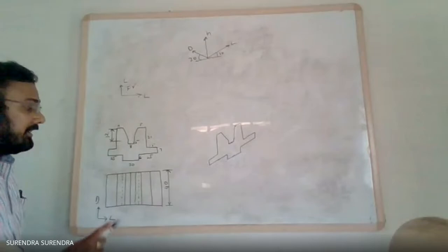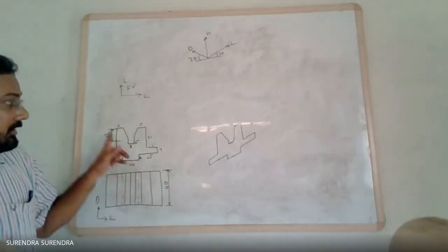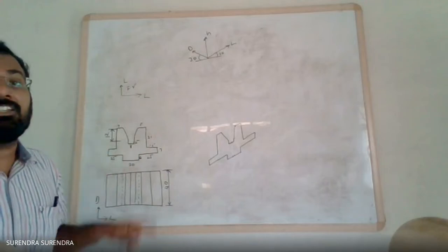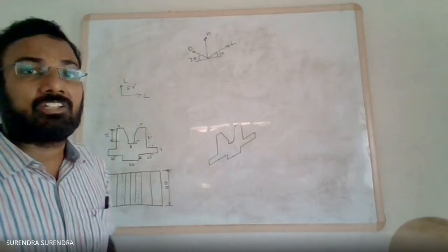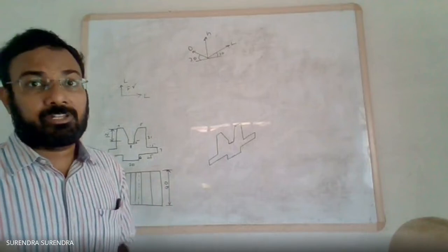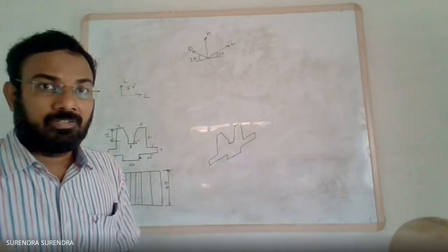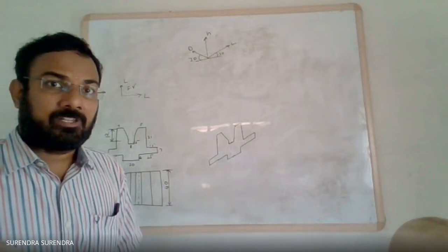Now the depth of the component is 50 mm. As there are no internal lines, neither hidden nor visible lines, it is a shape like a prism. A prism has the same shape throughout, as we just drew with the pentagonal prism and hexagonal prism.